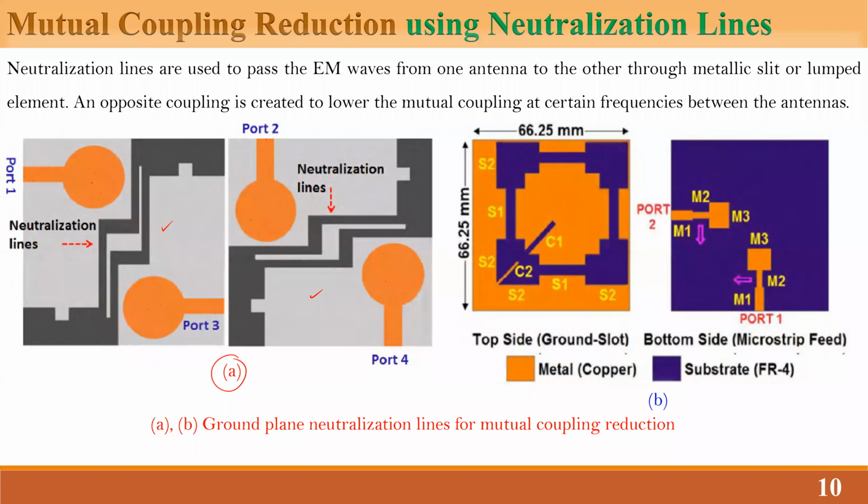Remember that whenever you are targeting MIMO applications, bandwidth is also important. You should not focus only on the mutual coupling; at the same time, you should also look into bandwidth improvement. If you do not get a good bandwidth, then there is no point in the 5G communications era, when you are targeting MIMO communications.